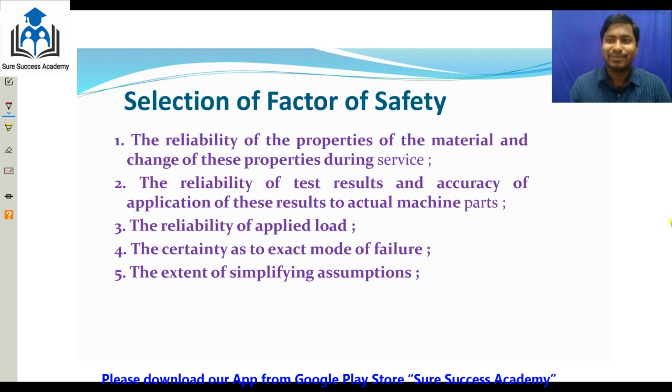No, it isn't, because the outside temperature is more, so the property of the material may change. I have found that the strength of the material is, suppose, 100 MPa, but outside it may be 80 MPa. But in that sun I cannot bring the specimen back and test again. So I can give the factor of safety. Suppose 100 is there, I will take 50, and outside you can work, that is not a problem in that condition. So these are different factors.